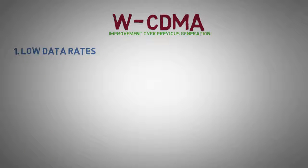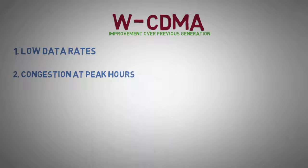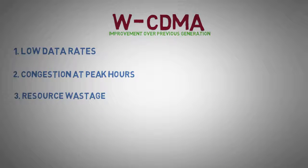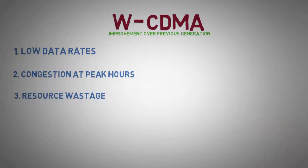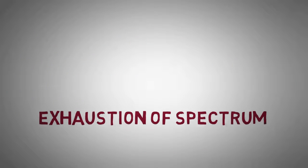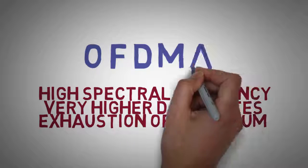In GSM, effective bandwidth for a user was only 25 kHz. Second, congestion at peak hours, as the frequency chunks and time slots were very limited. Third, resource wastage, resources remained idle when users were inactive. Fourth, poor spectral efficiency, due to guard bands and guard periods used to avoid interference. But exhaustion of spectrum, need for even higher data rates, and spectral efficiency led us towards OFDMA.